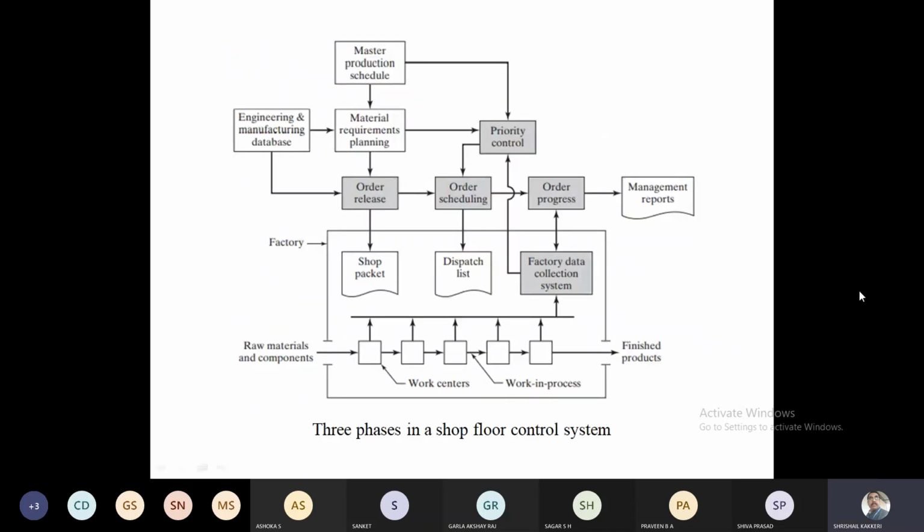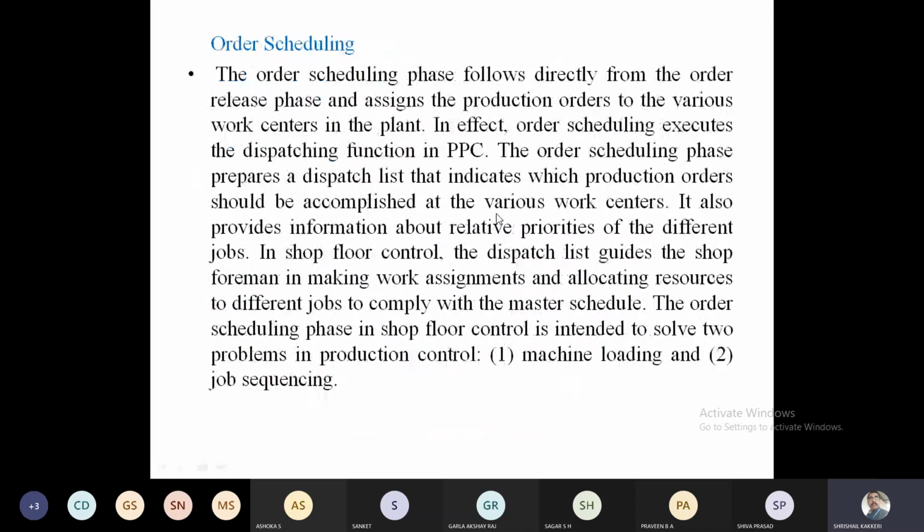If there are any variations, for example initially the A workstation required 8 work cycles and the B workstation required 12 cycles, and there will be a small variation physically, again this will be reset once again by taking the priority control. In the priority control, the headache of the buffer storage, the stockage, the flow of the material, and the conveyor distance and conveyor movement, all this will be decided.